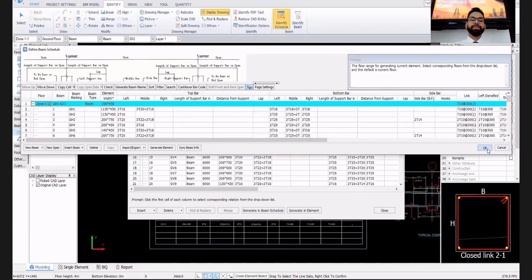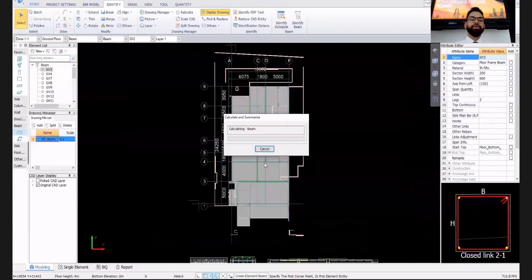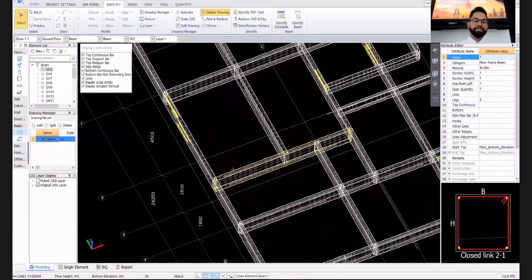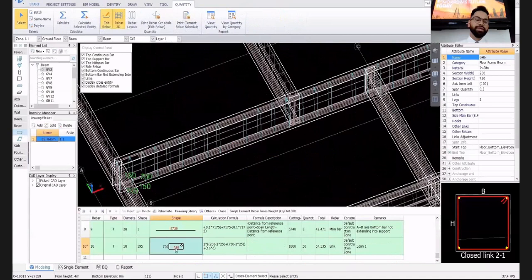just have a look at the 3D view. We can see the placement of rebars, the sidebars, the top bar and bottom bar with their stirrups, and the conditions of stirrups placement in their position. And you can see in the text view there are different details, and there is rebar information also with their respective shape and their bend length and everything in detail, which is quite useful for the bar bending schedule that we can produce also as a report from here. And then you have the details of calculation, the calculation formulas which have been applied there.